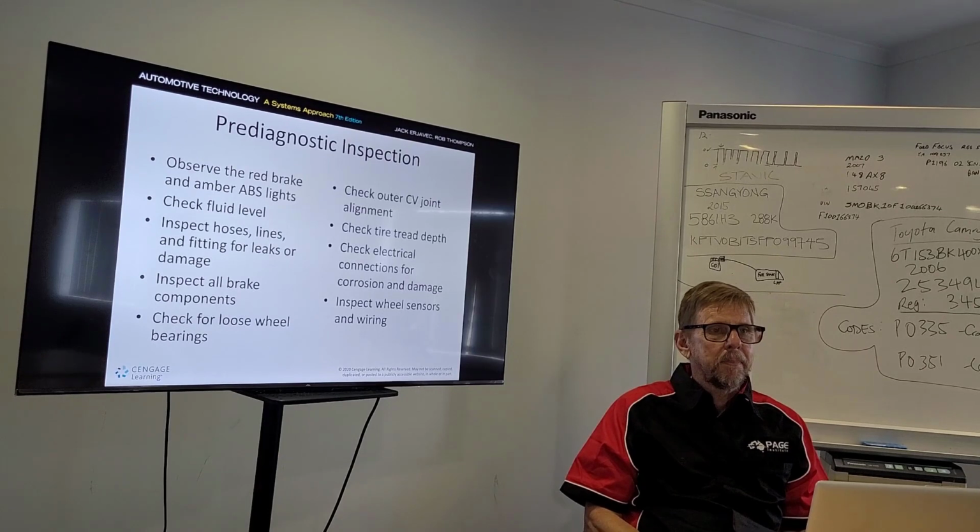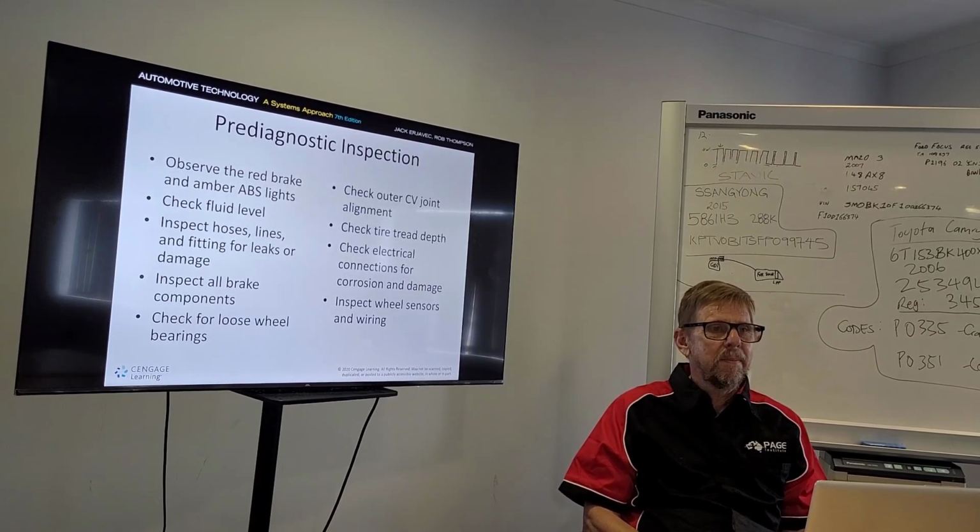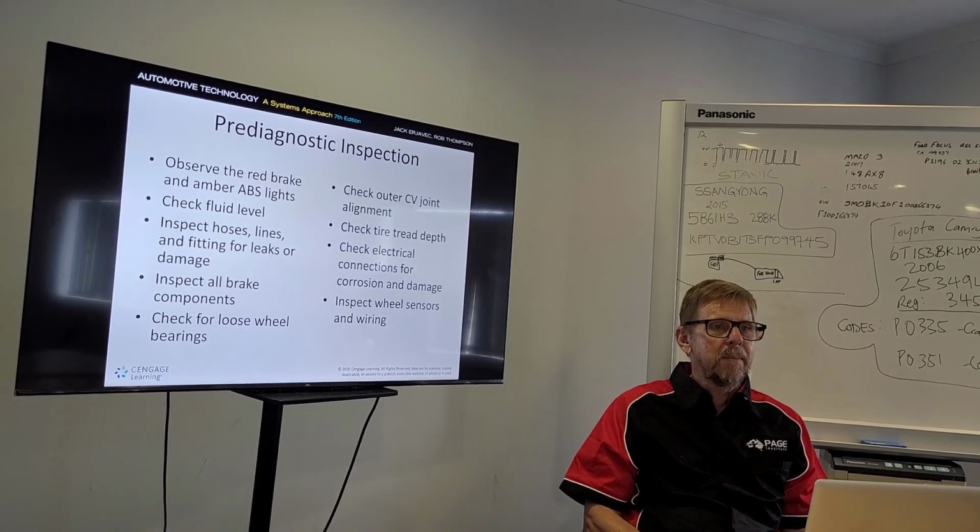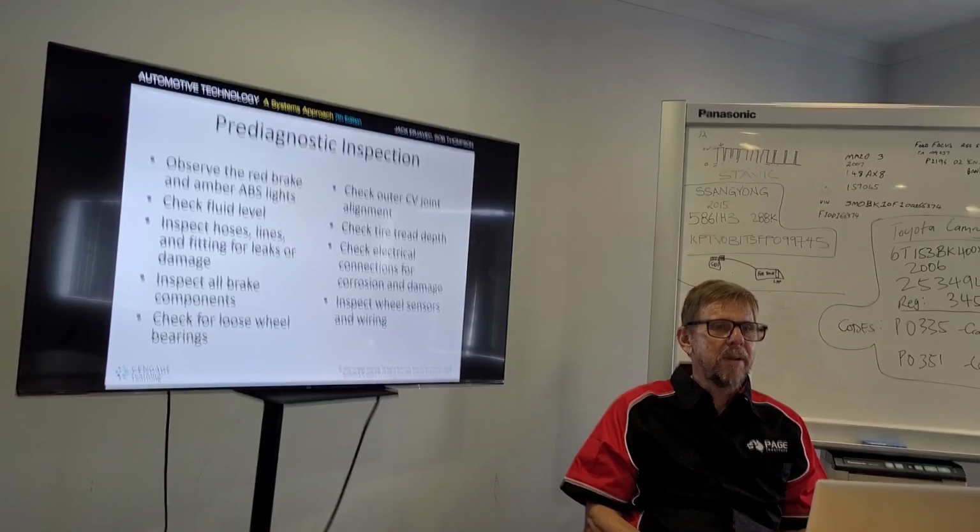One of my favorite tools is the mechanical stethoscope. Yeah. Now I check the wheel bearings like this. You can literally hear everything. If the alternator is making noise, or the pulley is making noise, you can pinpoint it. Definitely.